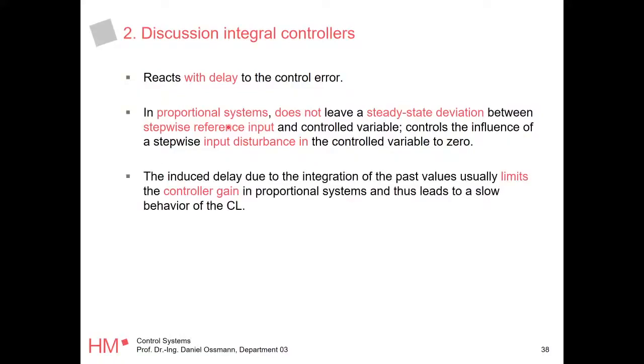However, the control gain is limited. You cannot increase the control gain too much because it will start to oscillate. And it will always lead to an unstable behavior if you already have one integrator in your system and you don't have any zeros in there, right?